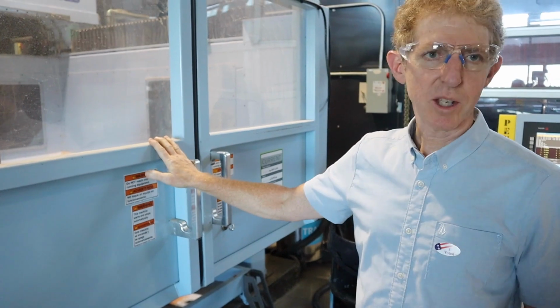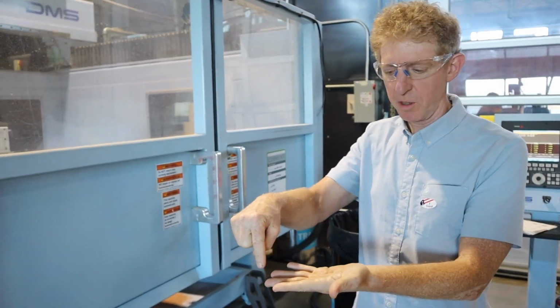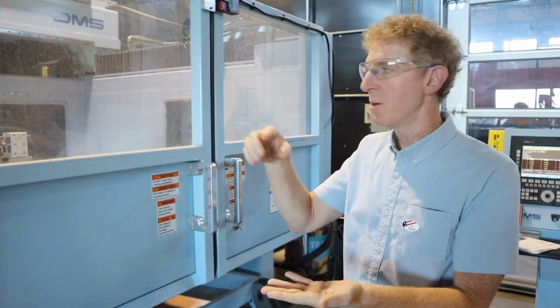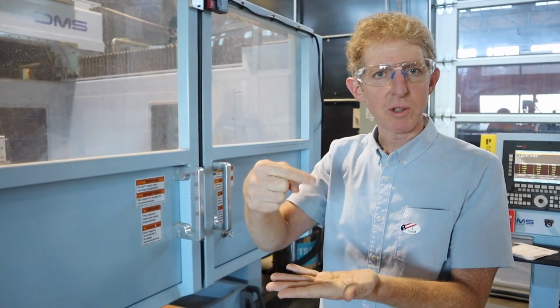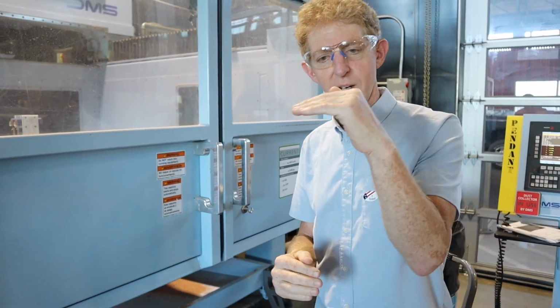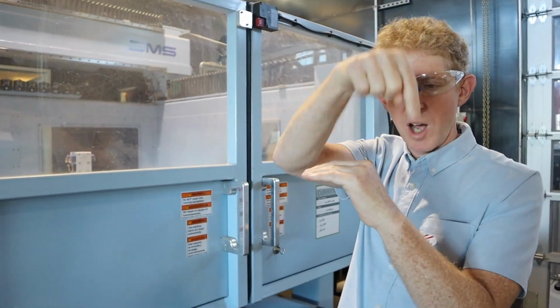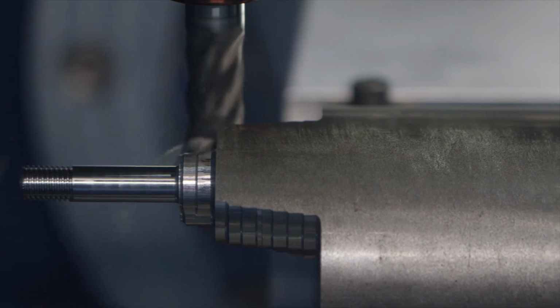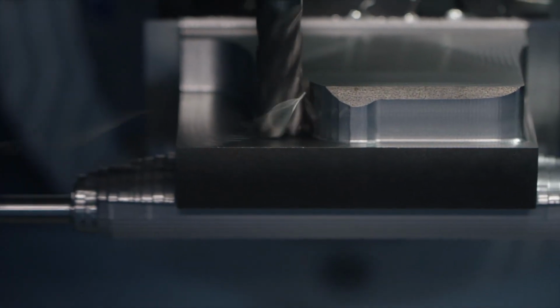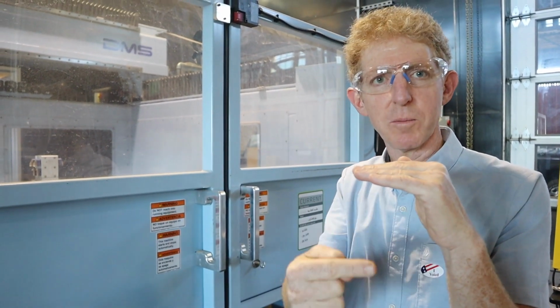When we talk about CNC machines, we start talking about dimensions of cutting. This device is a 5-axis. So when we think about the 3D world, we've got 3 dimensions, X, Y, Z. But this also has the ability to rotate the head. And so now you have 2 more axes. Now imagine you had a part with an overhang. If you can only come down from a top angle, for example, the water jet, you can't cut from the side. So with the 5-axis, you can come around, the head can turn, and it can carve from the side.